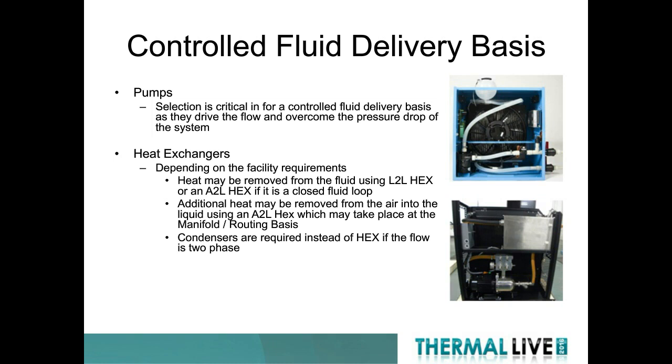Or if it's just the room that we have to remove the heat into, the air of the room, then we're using an air-to-liquid heat exchanger. Also, we can use the heat exchanger to take heat that might be in the air somewhere in the rack, and we can use that in reverse to actually move the heat into the liquid.